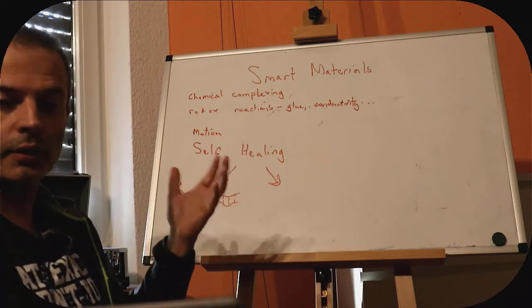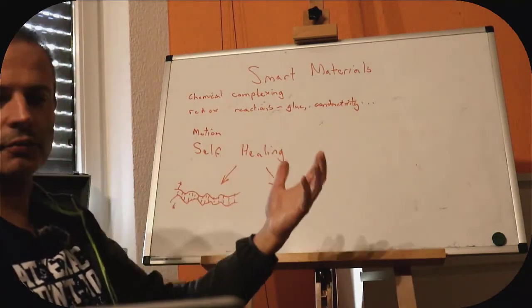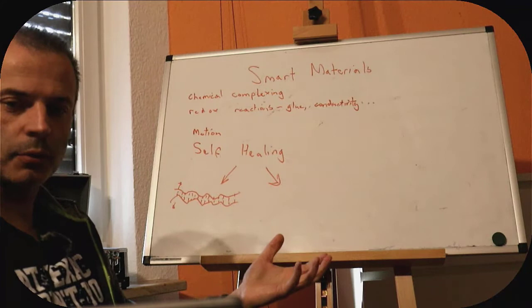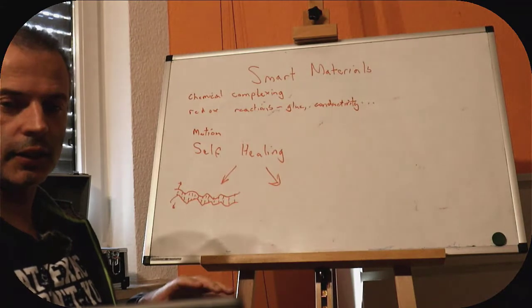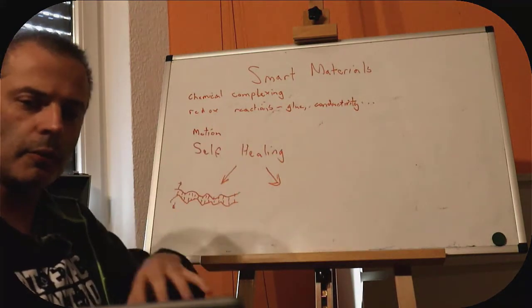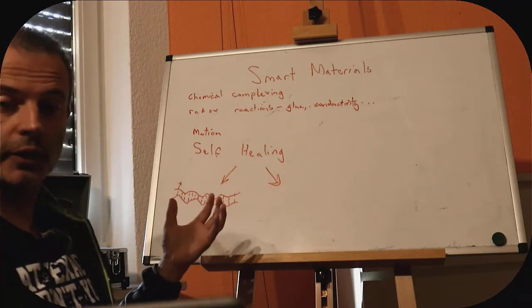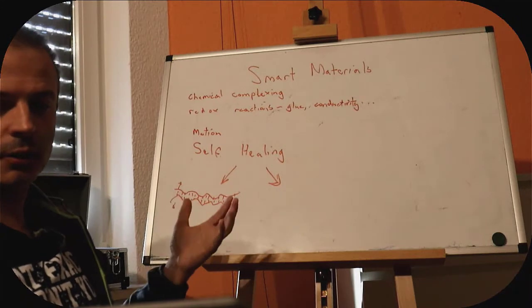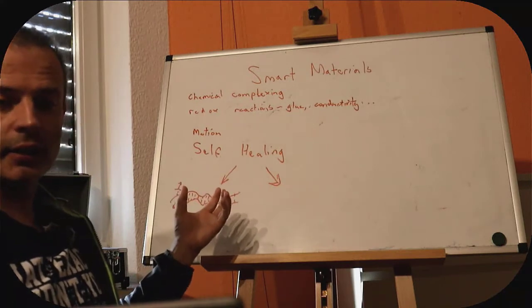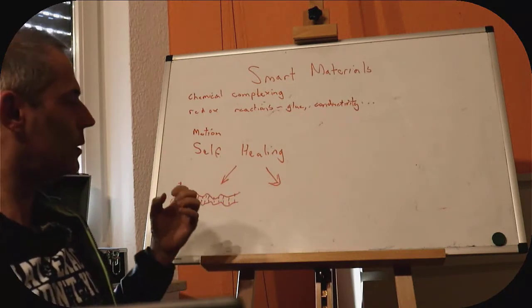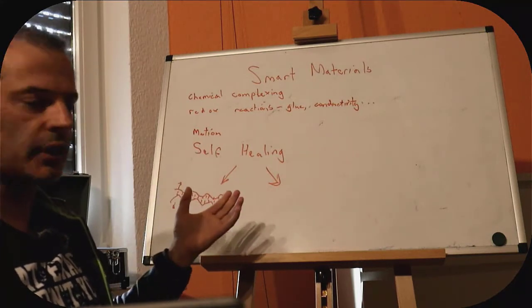If it's a polymer, so if it's some kind of hydrocarbon, it will be a trail of graphite, and that's obviously bad, but if we turn our power supply off, those particles will move away and it will be non-conducting again. And as long as we stay away from the bottom of the pot where it's going to fall to, then our non-conductivity will recover. There are types of silicone, which is like bathroom sealant, which are like that, but never set, and they never set deliberately because they can recover from mechanical and electrical damage.